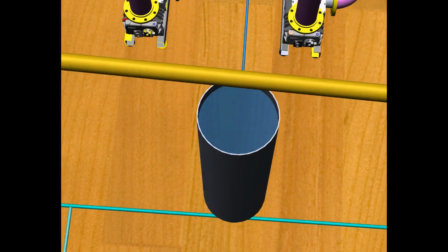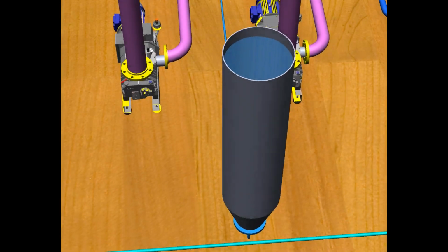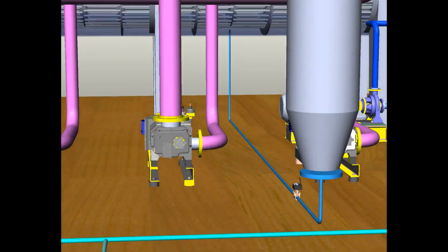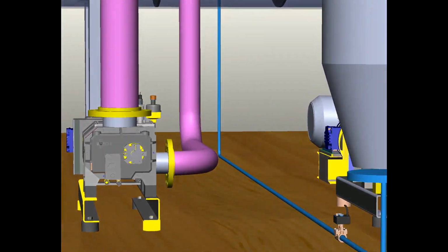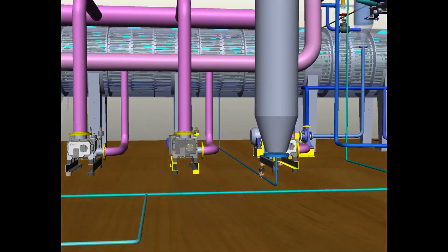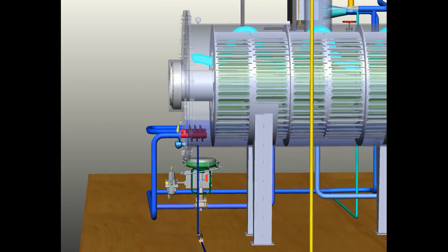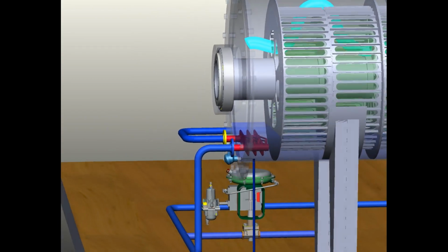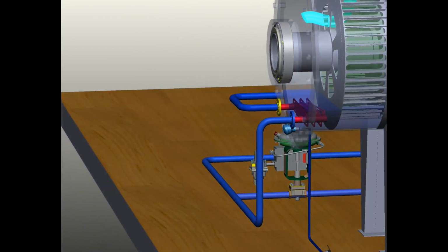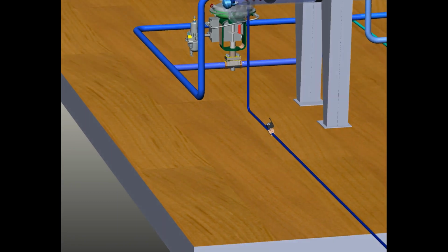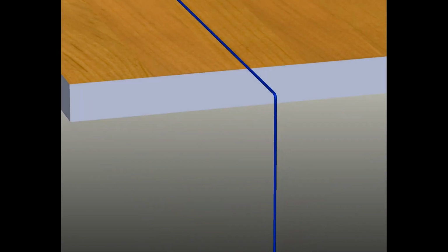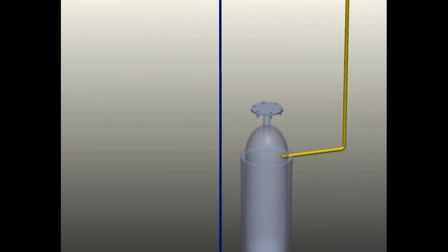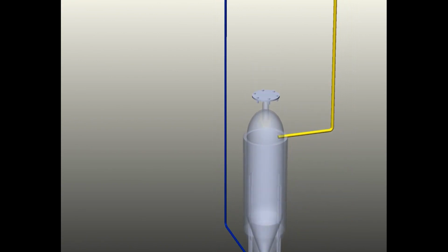The source water for isotope separation is fed into the lower central part of the apparatus under atmospheric pressure at a flow rate of 48 kg per hour. Draining heavy water from an apparatus with a pressure of less than 700 pascals presents a problem, since the pressure in the drain tank must be even lower. This is achieved by connecting the drain tank to the ejector and setting the drain tank at a lower level than the apparatus.